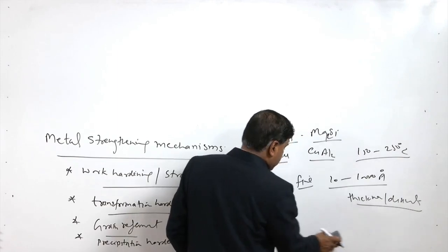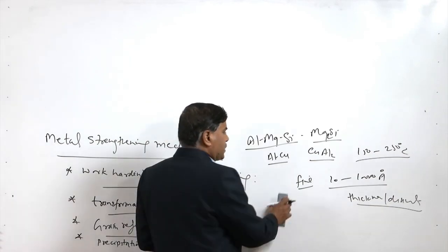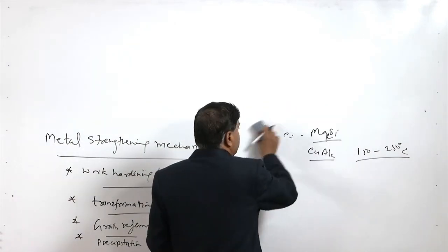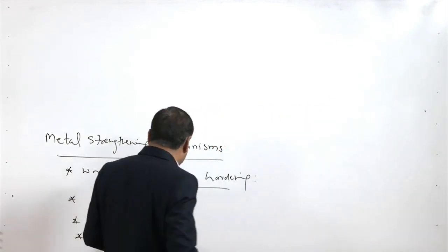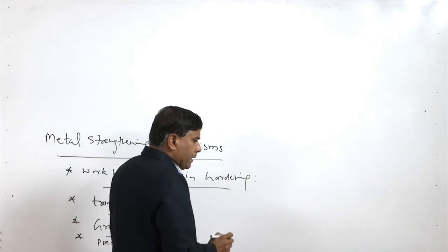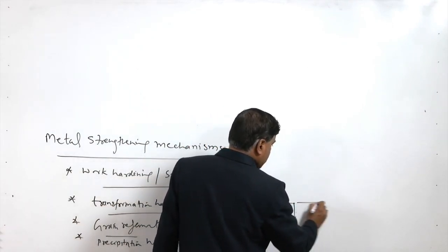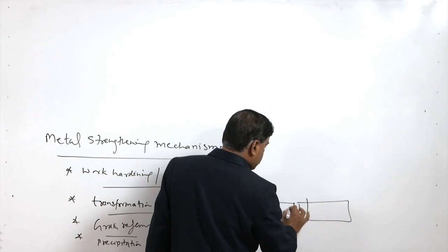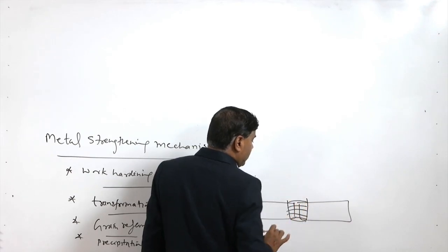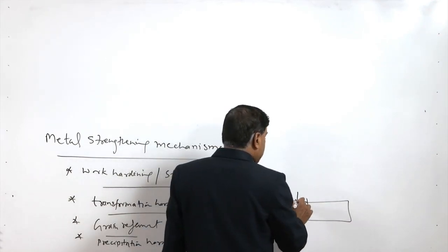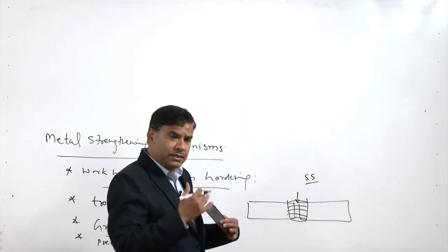So, in those processes wherever heat is used and the base metal is subjected not just to melting, but the heating leads to the dissolution of these precipitates, that will affect the mechanical properties of the material. There are two aspects. If one portion of the piece is brought to the molten state, of course all the precipitates will get dissolved, and everything will be in the solid solution state.